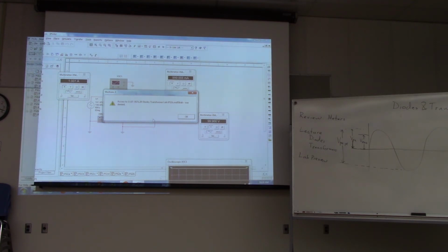And then the third thing you do is you subtract the resistance of the leads from the total resistance. That difference is going to give you the resistance of just the coil. Okay? Yeah? Do they make a DMM with dedicated leads that zeroes itself so that it automatically pulls that out?